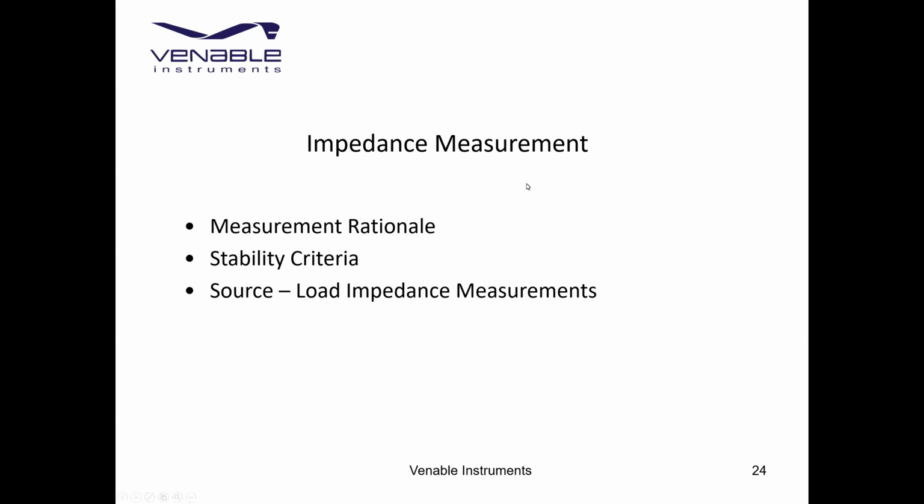So we'll go into our other major application of our instrument, which is to measure the input and output impedances of power supplies. This is really important in distributed power systems, where you could end up creating an oscillator by connecting the wrong power supply or the wrong number of power supplies to a driving power supply.